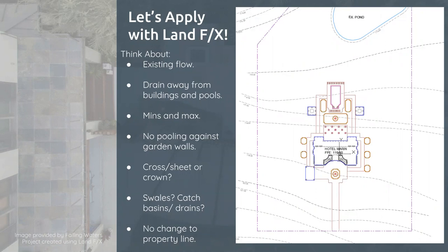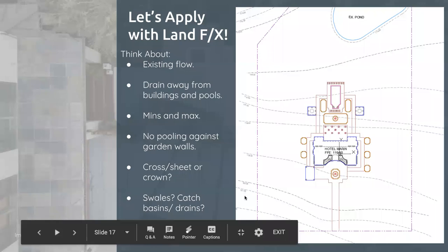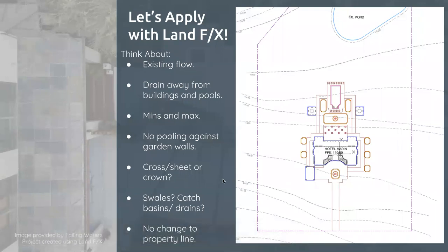So I have some contours laid out, and you can see the elevations. I always label the elevations on the high side of the contour, not the low side. So you can see it goes down 121, 120. So the 120 is going to be closer to the 121 than the 119. That's very basic of drawing and communicating contours.